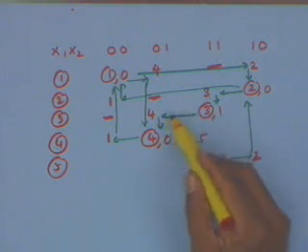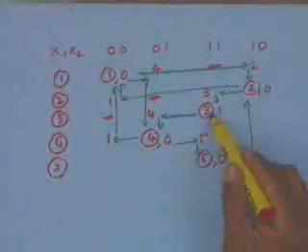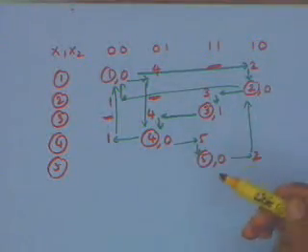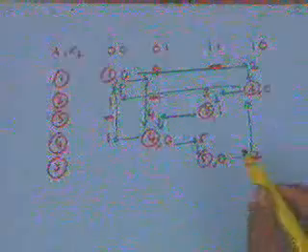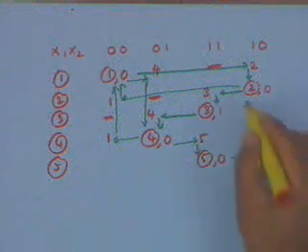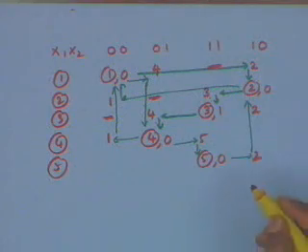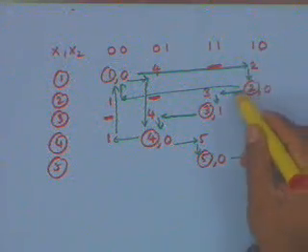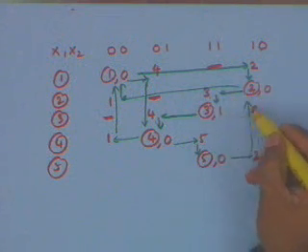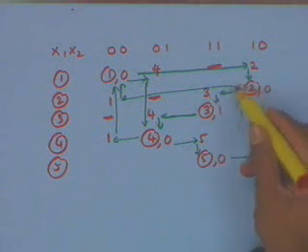So in this case 0 1 is already marked. I can even draw a waveform, but I do not have to do that. I know that if from 1 1 I go to 1 0, my transient state should be 2, because once I reach this 1 0, then if I get again 1 1, I can cycle through this, and I will keep on getting my output to be 1.